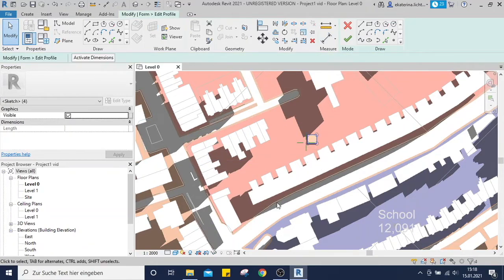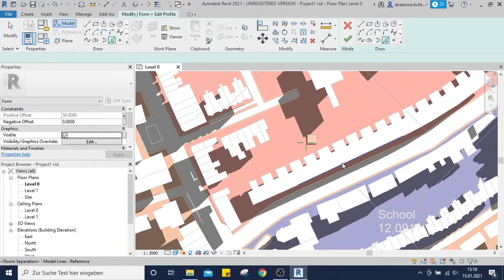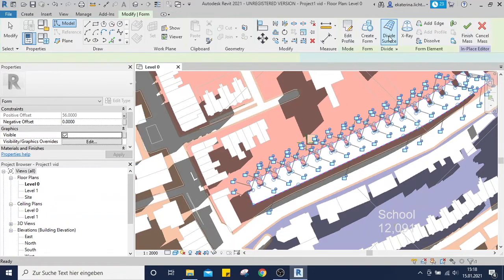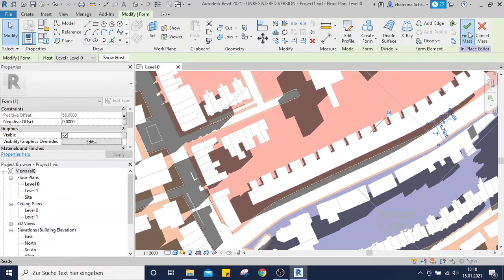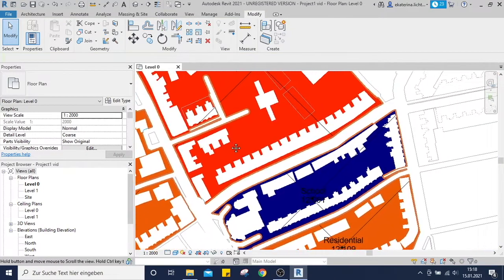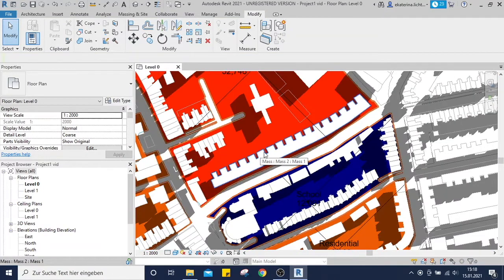I can show you here how you can trace existing buildings so that you convert them into Revit. So you select the footprint lines, and if we were to model this one, for instance, you tab yourself through, select the line, hit OK, and say finish method. It's quite a lot of manual work to actually get something done. And you wonder, hey, why can't we see this building?